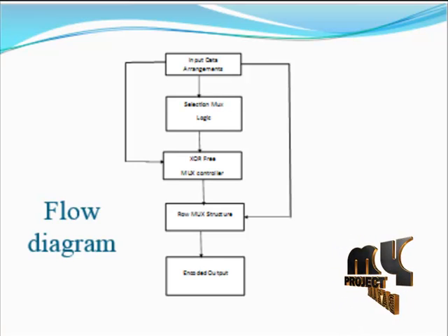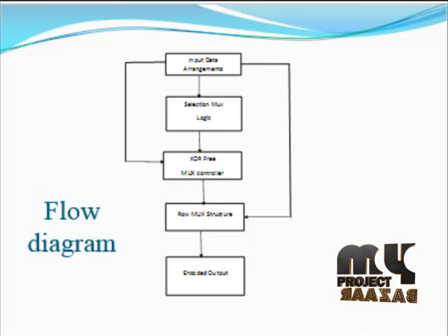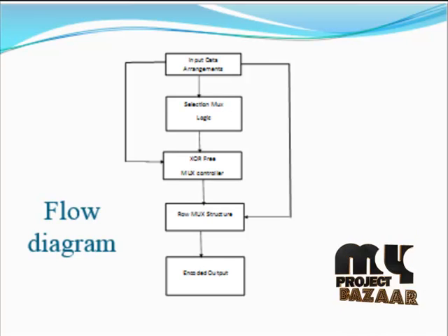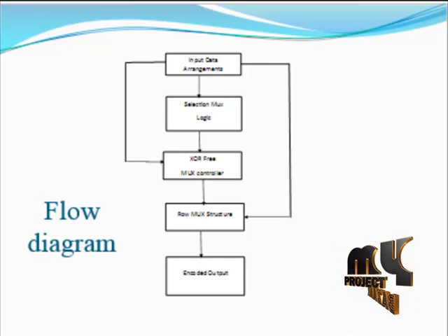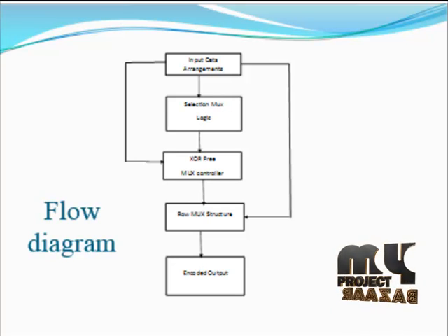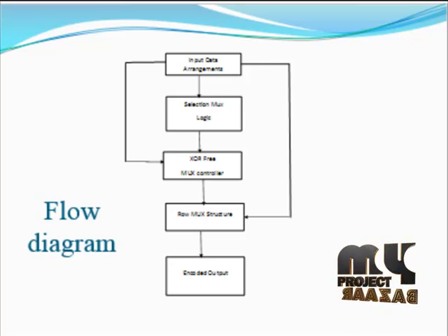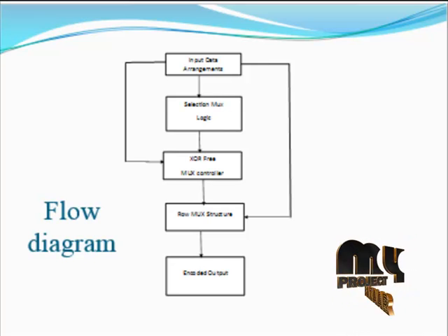Here a 32:1 mux is used to select a new ROM row from one of its inputs in accordance with the states. And then the second stage 2:1 mux is used to process the output of the first mux. The output of the second mux is combined with the coming LSB bits of the shift register to get the final encoded bits.